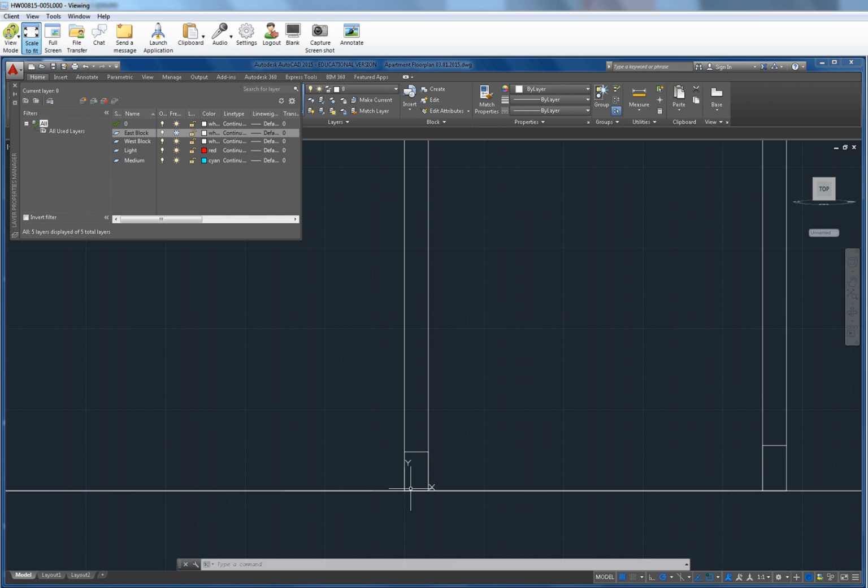I was trying to get you guys to do it all flat and then flip it up when it's ready to go. But if you're going to now draw on here, you have to move the UCS. So it's just UCS, and then you can click on a point and then move the UCS to be at that corner. So now the default drawing position is on the UCS XY.